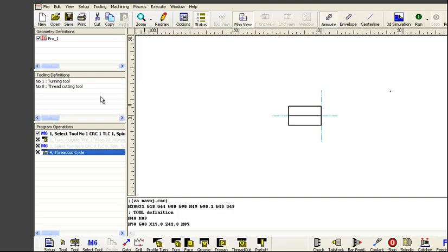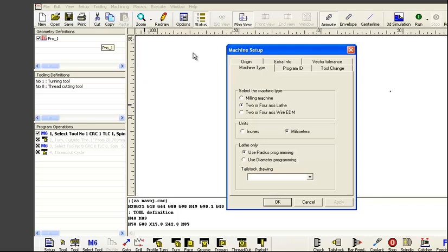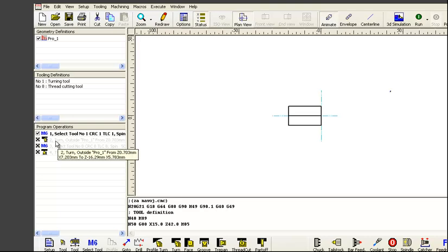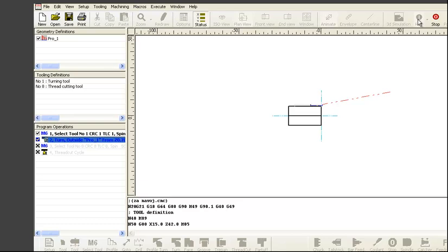And as I said, I defined safe home position according to my worst case scenario tool, my dangerous tool, my tool that can hit on machining part. So this is what I did here. And so now I'm turning my part.